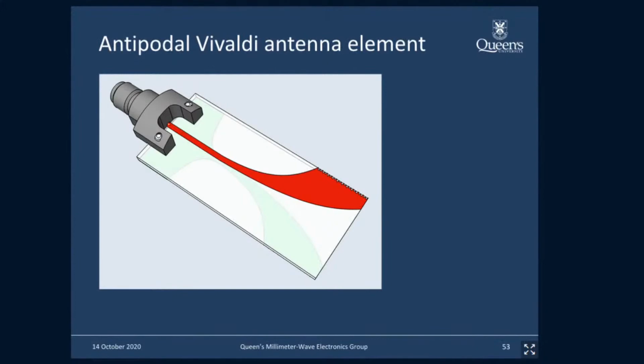The last thing I want to show you today is some very recent work that is about to appear in Transactions on Antennas and Propagation. This is an antenna with a lens incorporated into it, and you can tune the lens. You can do beam steering with this antenna by depositing fluid into the lens or removing it. To our knowledge, this is the first ever report of a fluidically tuned microwave millimeter wave lens, and it's integrated here into this antenna.